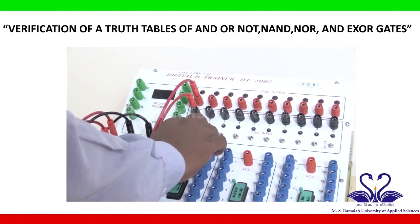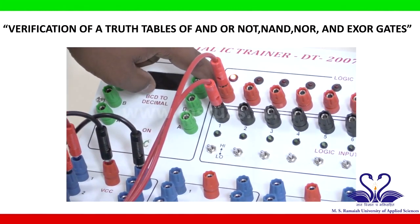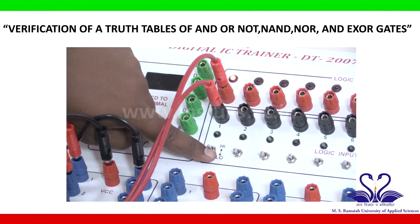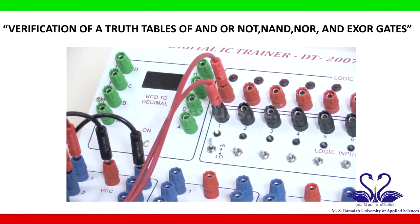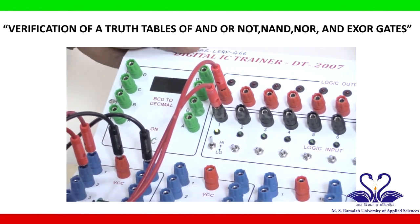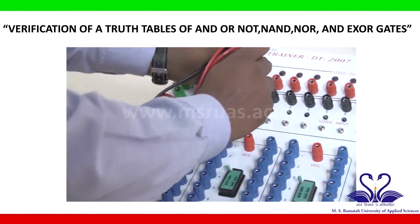Now turn on the IC trainer kit. For input 0, we are getting output as 1. If you make input 1, output is 0. So note these values in the given truth table. By this we verified the truth table of NOT gate. Turn off the power supply, remove all the connections, remove the IC.